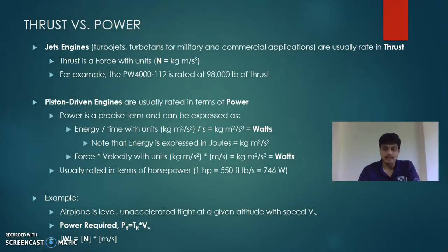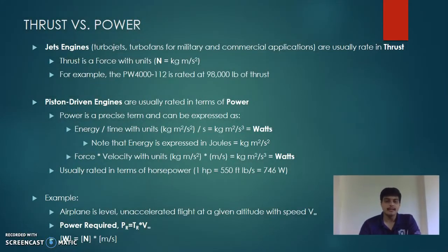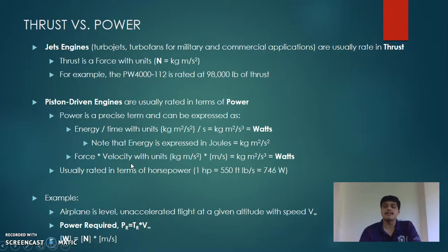The components, as we saw, are resolved, and so there is no requirement of the thrust. What do we need in terms of our thrust requirement? You simply see that power required is thrust into velocity, and so it is Newton into meter per second. So it is a power rated engine that you will use, and if you use a power rated piston engine, you will have to specify what wattage is required by first computing the velocity and then computing the thrust required.